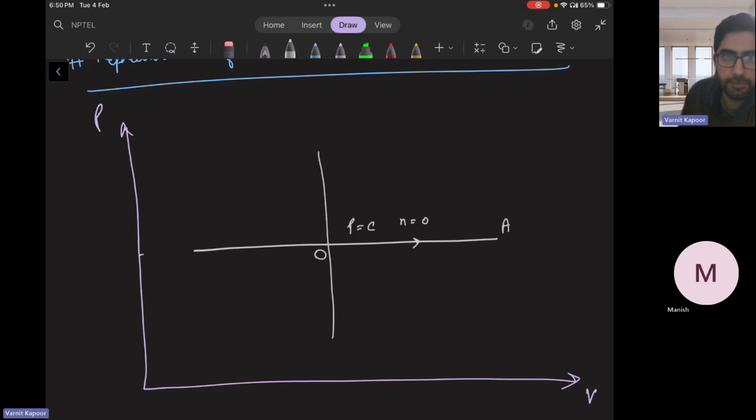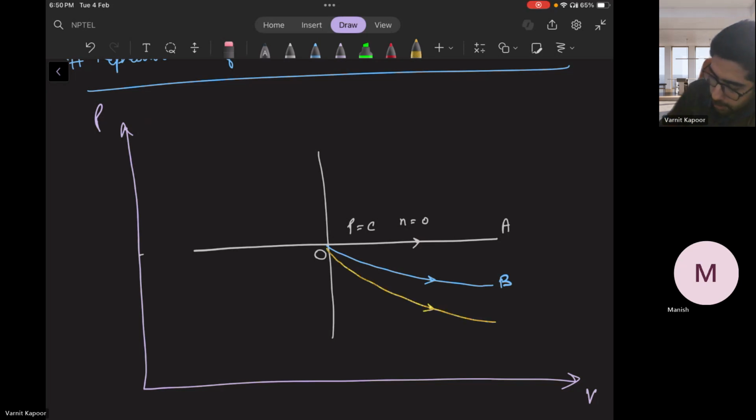Next, an isothermal process where n will be 1. So PV is equal to constant. So it's a rectangular hyperbola. So here, expansion. I'm talking all about expansion from O to B. Next is the adiabatic process, O to C. That also follows the same. And the last one is, you can choose, polytropic, D. All are expanding from O to A.